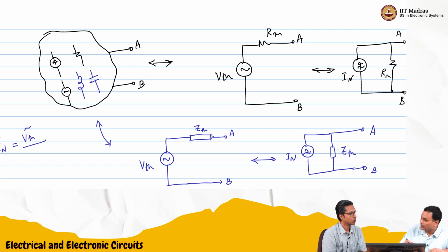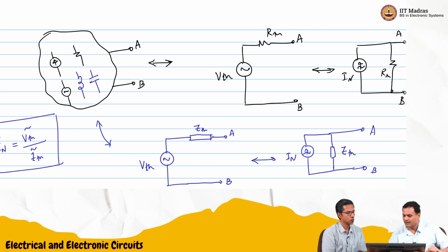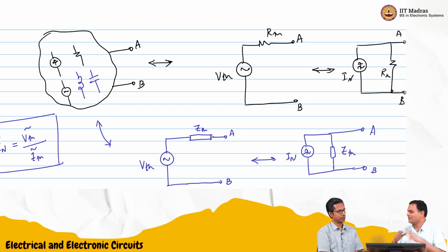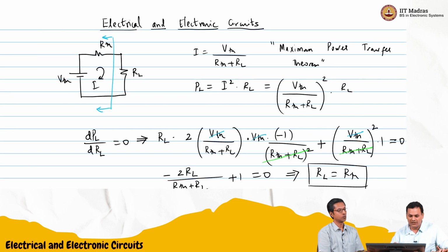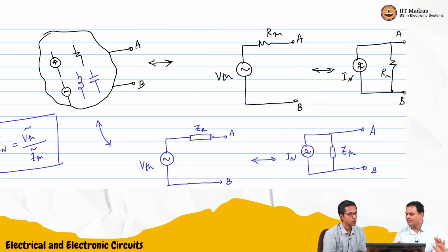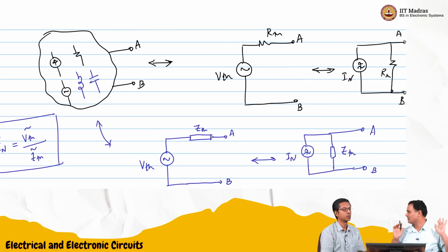Yes, exactly. That's what we are trying to say, right? Maybe I'll just write it in complex form like this. So I think now this is basically Thevenin's theorem for AC. It is just a straightforward extension of what we did for DC. For DC, we said it is just VThevenin, RThevenin. Now we are saying it is VThevenin, ZThevenin, where both are complex numbers.